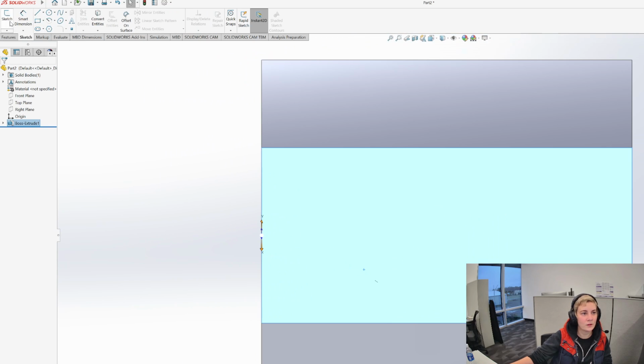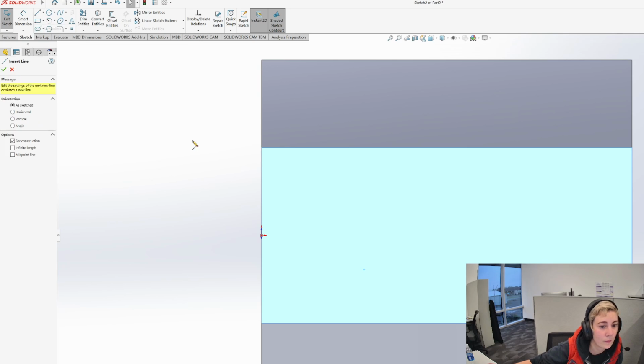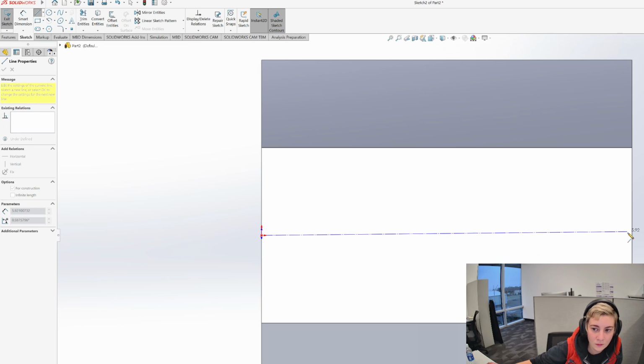And then we're going to go sketch, and it's going to show your origin right here. I think you're going to make a center line going straight across, starting at the origin. And that's going to be horizontal.